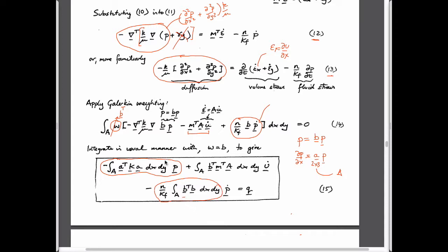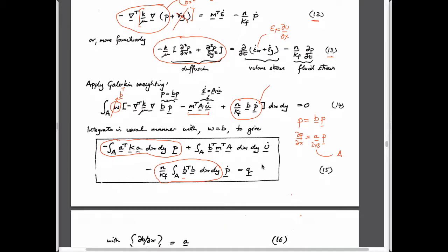And so we have a component which is our normal conductance matrix and two linking terms. The first term is due to the fact that compressibility of the fluid will give us some effect. And the second is that if we strain the porous medium, there's a certain amount of fluid that will get squeezed out. This whole equation is written in terms of fluxes, volumes per unit volumes if you like. And so if you squeeze with a displacement or with a strain, you end up squeezing a certain amount of fluid out of the system, depending on the rate at which you're straining it.